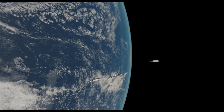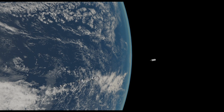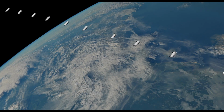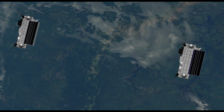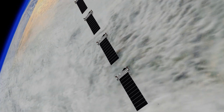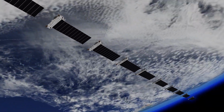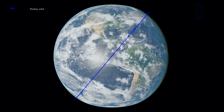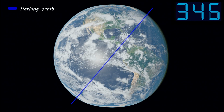Hereafter, the second stage will be deorbited into the Earth's atmosphere. Once the spacecraft have distanced themselves from each other, the solar panels are deployed. Now the satellites are in the low drag configuration. At this stage, any faulty satellites will be deorbited. Remaining satellites will fire their Krypton thrusters and reach the 350 km parking orbit.